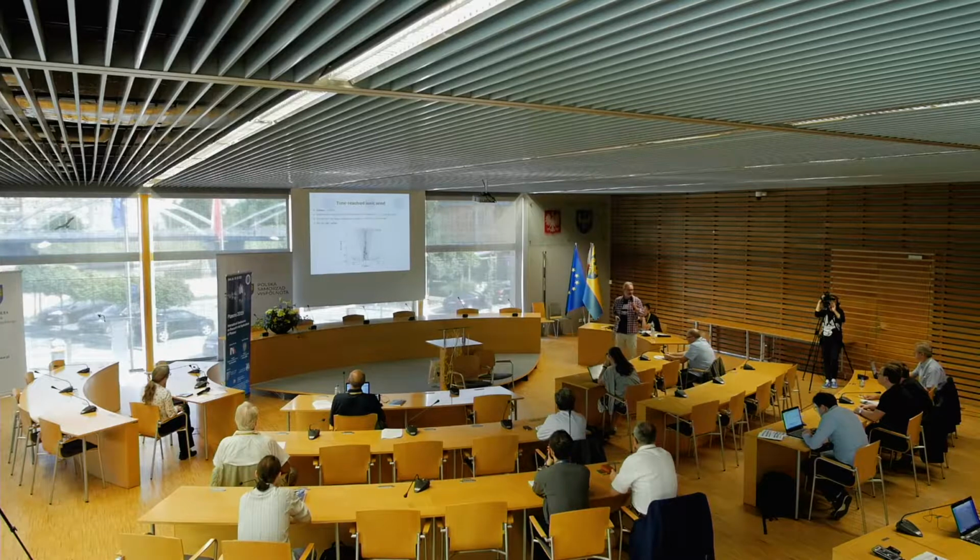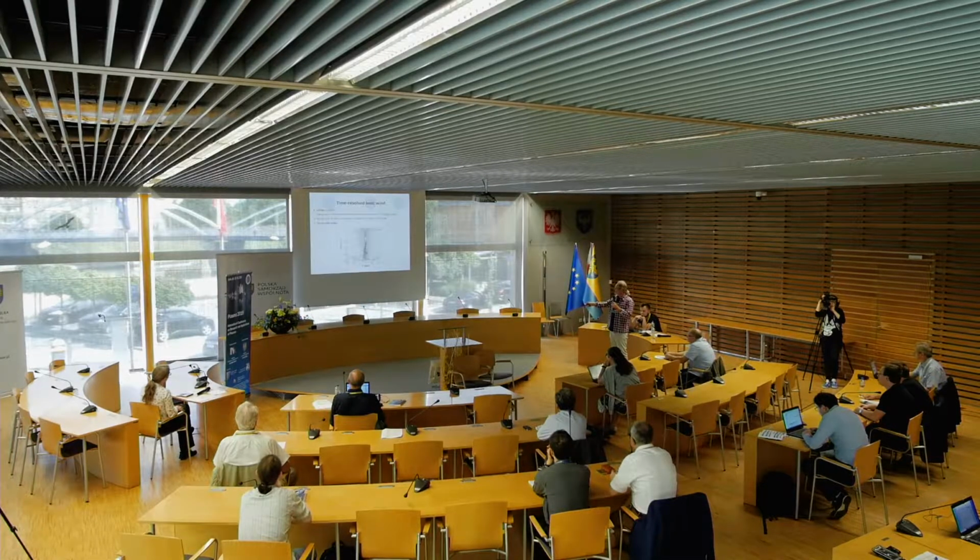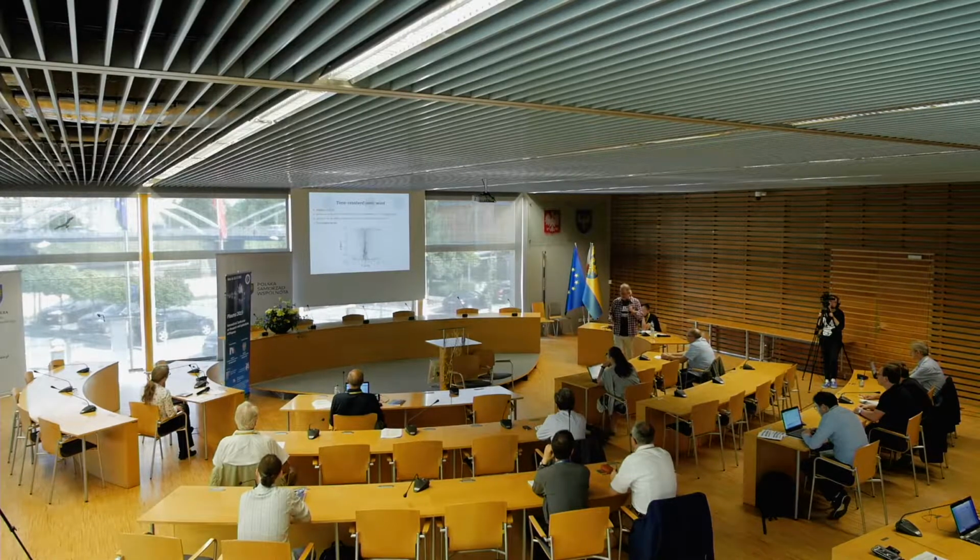Now if we observe the time-resolved ionic wind, I am going to show you several instantaneous velocity fields at different instants: here at 1 millisecond, 2 milliseconds, 4 milliseconds, 8, 12. We can see, as I showed previously, that the jet starts from the needle and propagates in quiescent air and impacts the wall, forming, when it impacts the wall, a three-dimensional circular vortex.